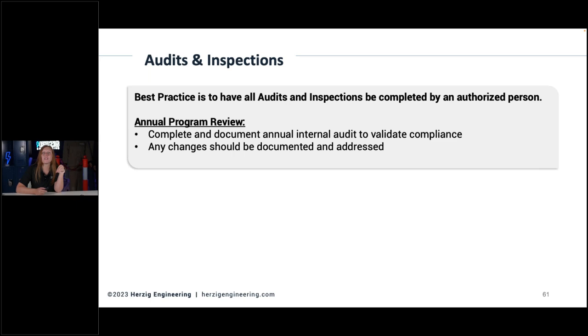You have to verify absence of voltage at each point of work, where they're going to stick their hands, not just at the isolation device. Because there could be backfeeds, there could be a secondary source. Just have to double check all that stuff. Anyway, little side tangent there, but you do still need to review at least, and possibly update, that written document every year as well, even if OSHA regulations don't update every year. There are other factors.